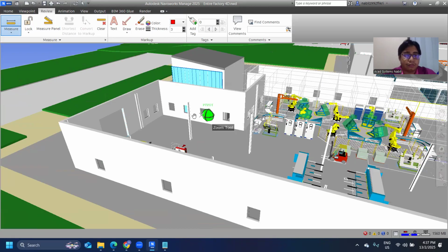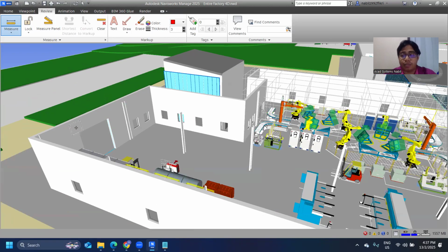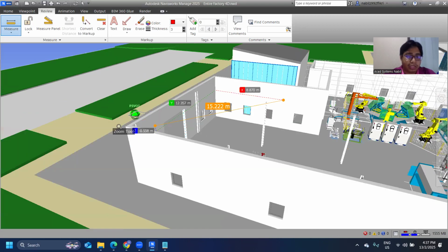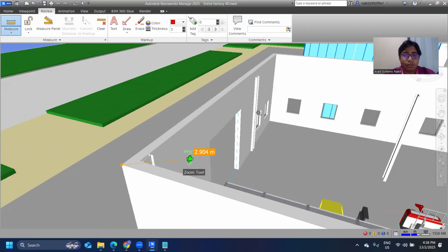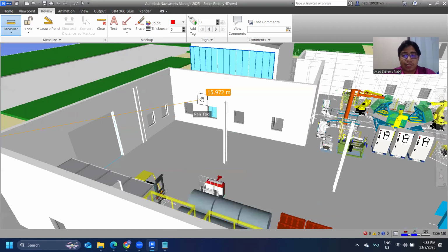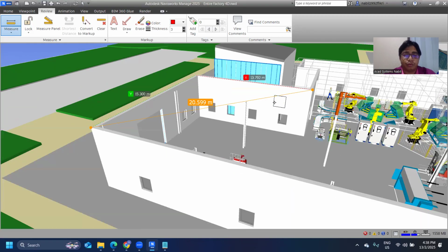If I select point to point, this basically allows you to select from one area to the other area. Either I select one face to the other face, or I can also select based on points. To select based on point, you can go to any edge and make sure the symbol for X appears. Then it will allow you to select a point instead. So that is basically point to point.